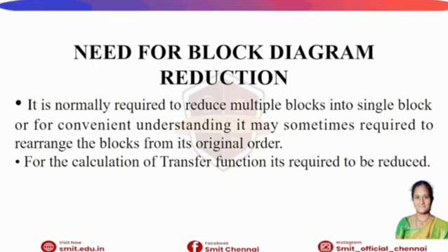Need for block diagram reduction. It is required because practical systems contain many blocks, which makes analysis difficult. For easy understanding, we reduce multiple blocks into a single equivalent block. Reduction is also necessary to calculate the overall transfer function of the system. So block diagram reduction simplifies complex systems.